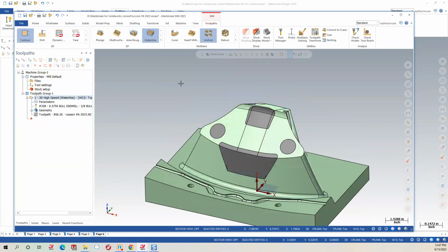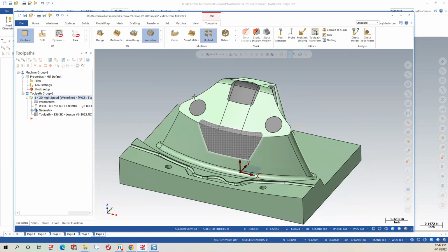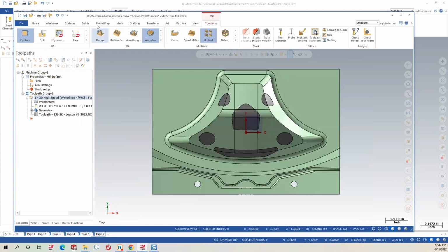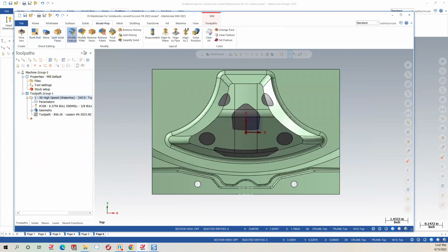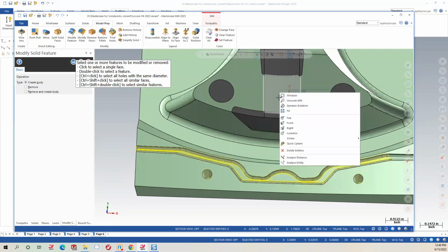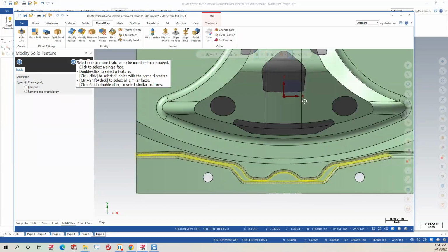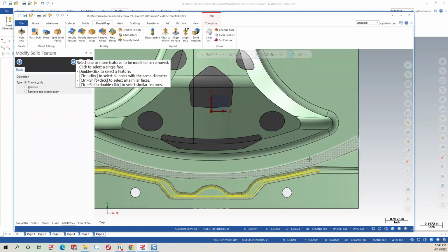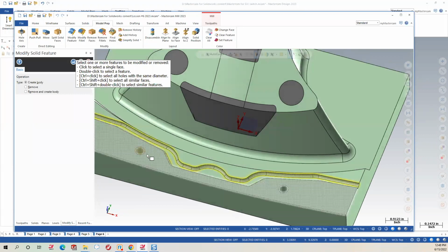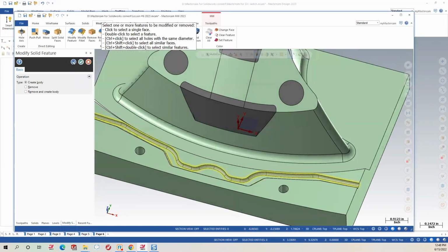That's a very quick, fast way of plugging your part, getting solids going, and creating another plug if you want to. Model prep, modify a feature, create a body, and can I window select this? Boop, I got it off my screen a little bit. Got most of them. Top, pull the shift key down and the mouse button down. I missed a few. Window again, there we go. There's all the geometry. I got a couple of holes that I don't need. That's all right.